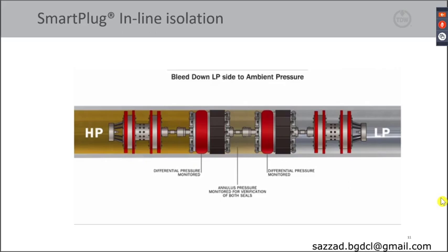The Smart Plug tool provides full double block isolation using 200% independent isolation plug modules. Each plug module is capable of isolating the full pressure of the pipeline, giving the other 100% contingency.